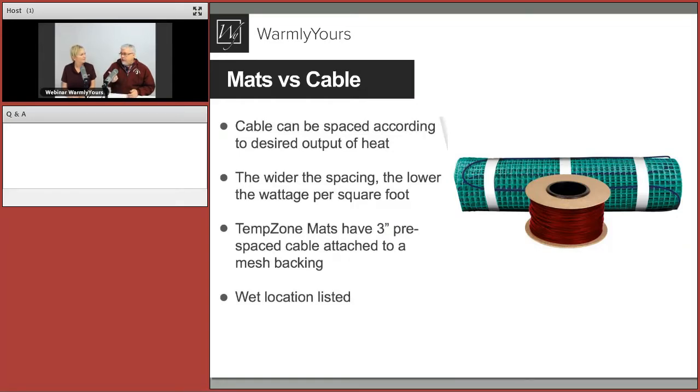So I know in your basement, we did a job where we are over an insulated concrete slab, and we took the cable itself and spaced it at 4-inch wide spacing. Yeah, it's a large room, so I didn't have enough electricity, so I wanted something a little more flexible. So I took the cable, just spaced it a little further apart, insulated the slab, and we'll be talking about that very shortly. As a result, I could get something that was warm, efficient, but I used less product and I used less electrical.